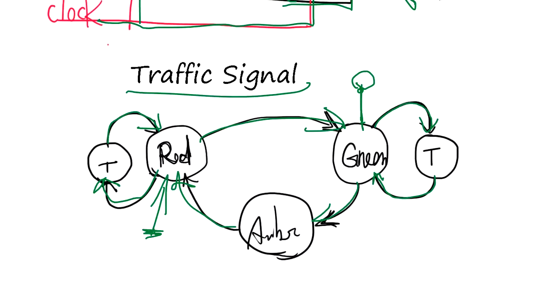And in this state diagram, to each state you assign a logic state. If it's 4-bit, green is 0001, amber is 0010, and red is 0011. And here's a detection and if condition, right? A logic if condition.